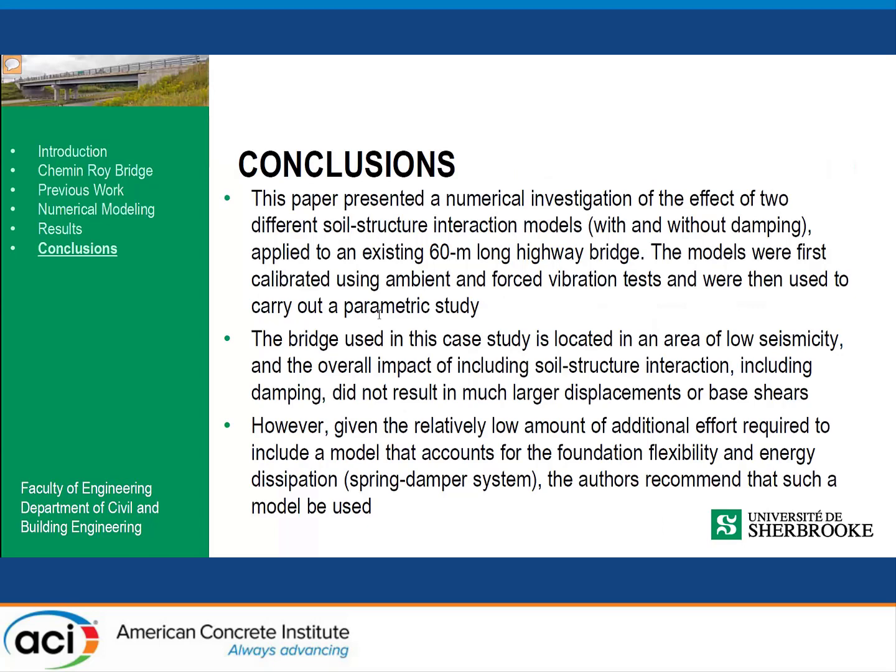So the conclusion: we presented the case study, a numerical investigation of the effect of two different simplified soil structure interaction models with and without damping, on a model that was calibrated using ambient and forced vibration tests on a real bridge. We have to notice that it is in an area of low seismicity. So the overall impact, I must say, of including the SSI models did not result in much larger displacements or shears.